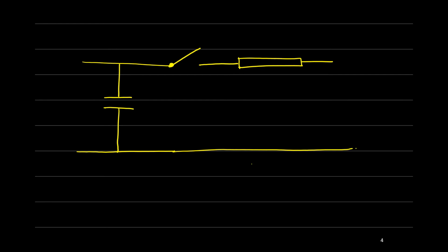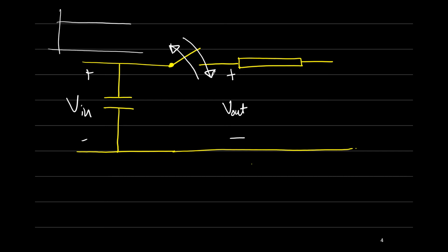So the switch here is on and off all the time, frequently, and the voltage V out will be taken just after the switch directly, and the Vin will be on the input, on the capacitor, and it will be a constant voltage, Vin, like a DC input voltage. Let's see how the voltage on the output will look. Let's draw the time versus the V out.